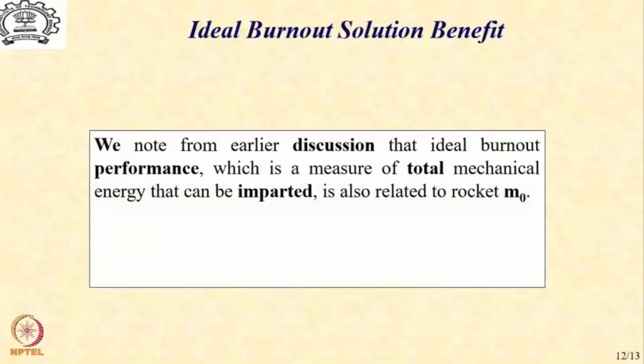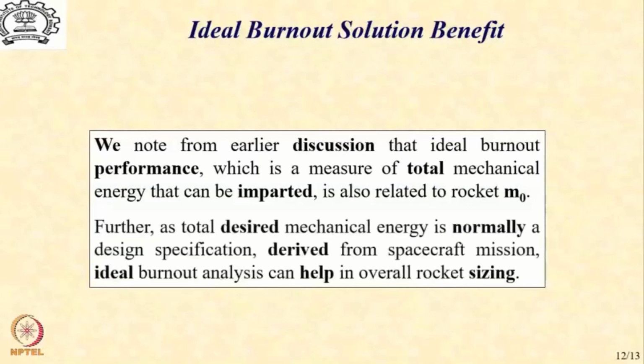Which means it will tell you which rocket will do the job, or whether there is such a rocket which can do this job. Which means you can also talk about feasibilities of the design requirement. Suppose you put a requirement which is not really practical or feasible, it will be possible for you to immediately check without any computational effort at all. And then we realize that the simple analysis that we have done can help us in overall rocket sizing without too much of computational effort, and it's a reasonably good solution, you have to understand.